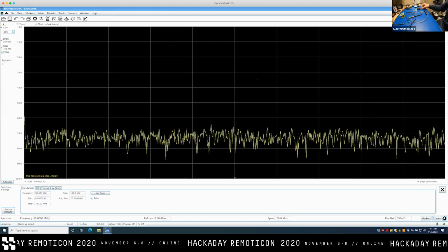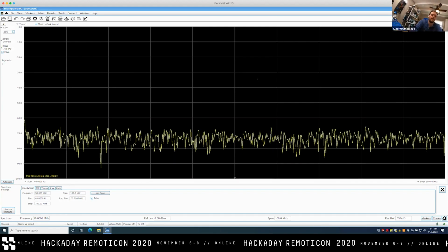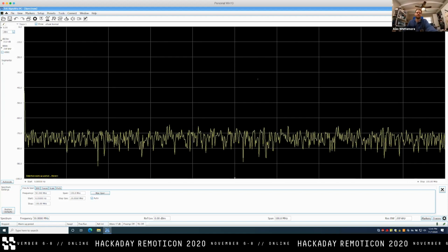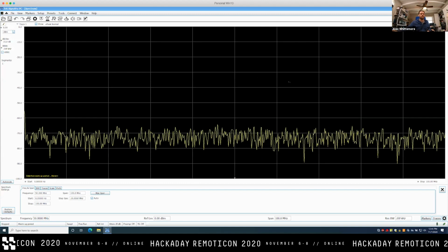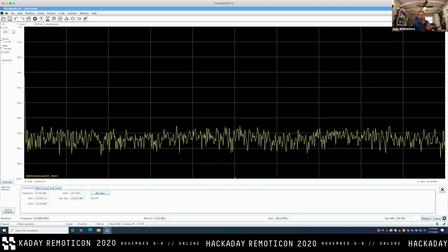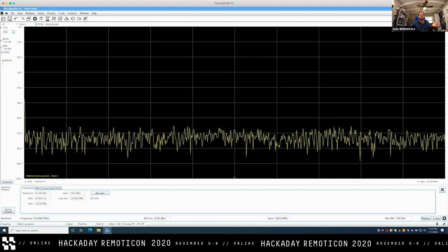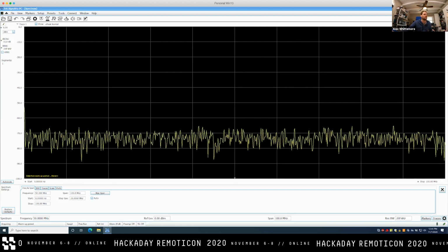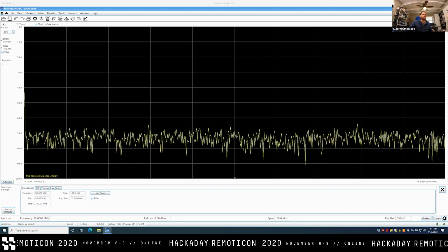So at this point, we have a halfway decent idea of what noise sources exist on our board and what's going on. And let's just assume that you were looking in this range because you had a 60 megahertz failure in your test report or something like that. Although you can just hunt arbitrary signals this way. It's just if you don't know that they're failing yet, then it might not be worth your effort to try to correct them. But sure enough, we've got those loud signals. Let's see what they might be.